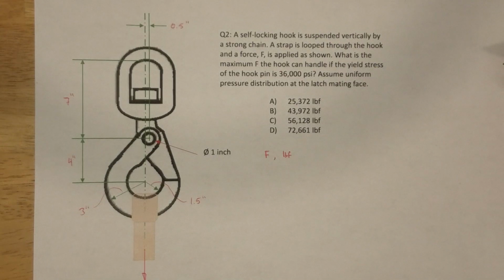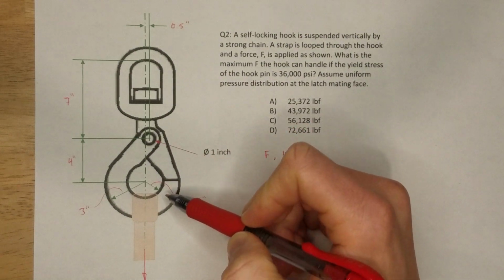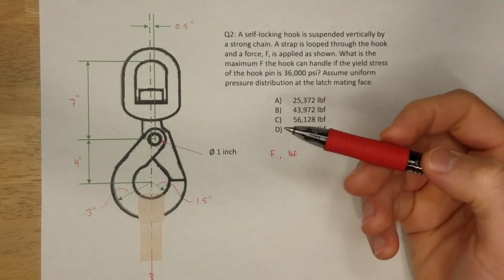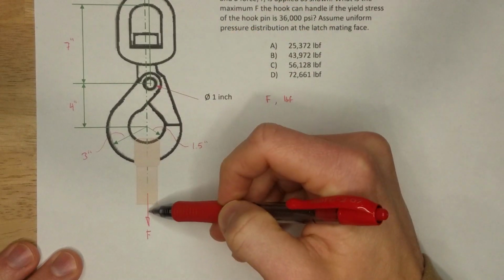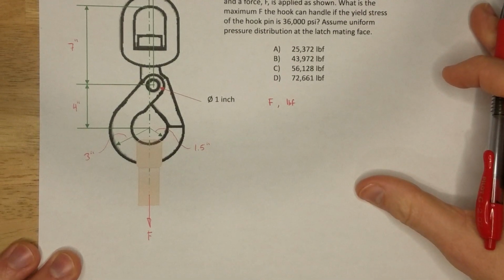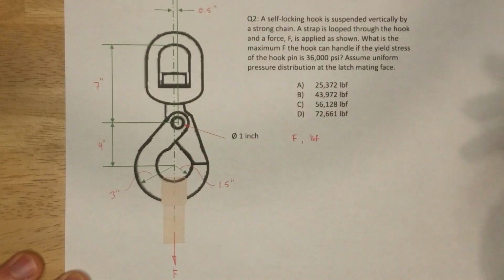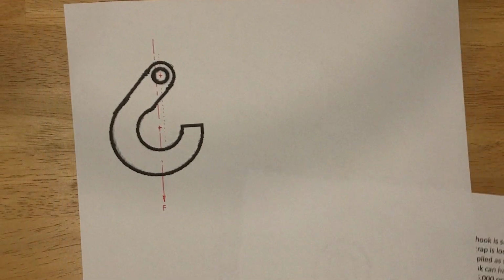Let's breathe for a second and look at this. We have a diagram and a fairly confusing one. A self-locking hook is different from a normal hook in that the bottom half is pinned to the top half. When there's no load, this bottom half can swing freely. But when it gets under a load, it locks itself. So we've got an off-center pin here that's not in line with the load. So that's a little bit strange. You've got a lot of dimensional information here and unique info about this pin. Good. So we've got some indicators. What's our first step that we're going to do is go straight into a free body diagram.